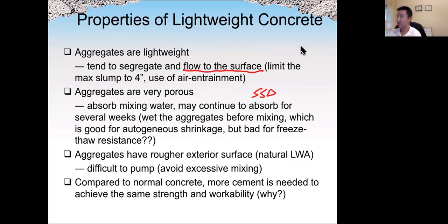That may change the water cement ratio in the cement paste quite a lot compared to what we design. To compensate for that, we could wet the aggregate before mixing, so the aggregate is at least in saturated surface dry condition before we mix it with the other raw materials, the cement powder and water.